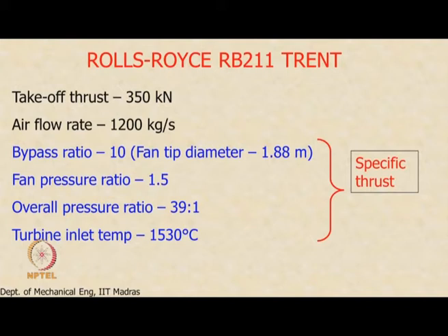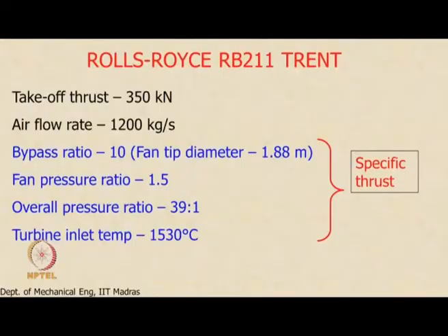What is challenging and interesting about this is the temperature of 1500 degrees Celsius. If you recall from our earlier discussion, we showed the engine: the air goes into the combustor where we raise the temperature to about 1500 degrees Celsius, then it comes to the high pressure turbine. This temperature is about 200 to 300 degrees Celsius above the melting point of the blade metal, and still the blade does not melt. That is what is challenging and interesting about this technology, that the engine can operate at temperatures about 200 to 300 degrees Celsius above the melting point of the blade metal and still continue to operate without any problems.